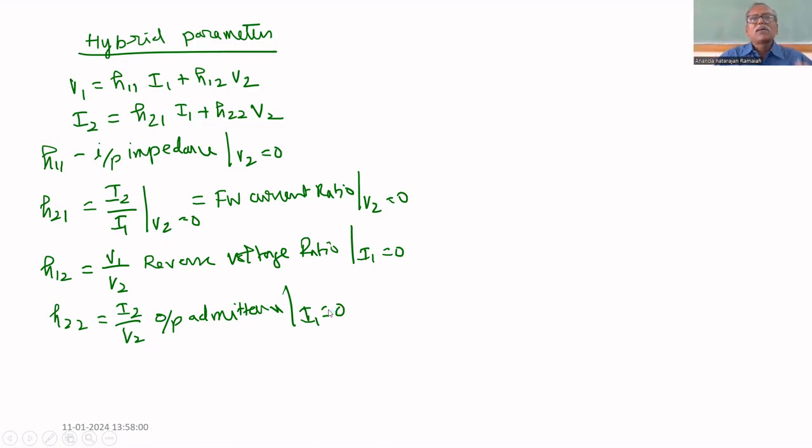The parameters are multiplied by I1 and V2, input current and output voltage. If you remember this, in the input side you won't get any confusion. I1 and V2, first voltage, then current. The left out are V1 and I2, that you can write in the input side. But you have to remember this I1, V2. No other go.